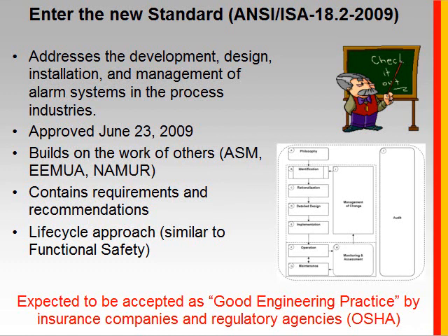In terms of a standard, it contains verbiage that tells you what you must do. The requirements and recommendations are clearly spelled out in the ISA 18.2 standard. These other sources contain a lot of great information, best practices information, but they're not formulated in the form of a standard that demands compliance.